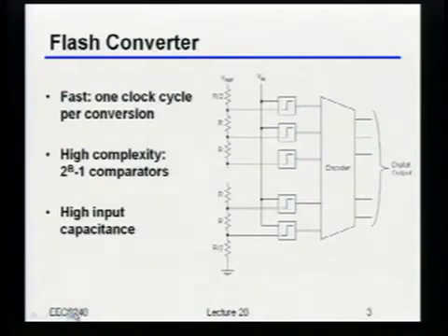So we'll see all of these things in 1 second, but this is just an additional piece of motivation as to why comparators might be interesting. We've already talked about it in the context of high-speed links, but these things are used in many other places as well. One really obvious place is in analog to digital converters. As an example, you could come up with a so-called flash analog to digital converter, where the idea is very simple. You just have a bunch of comparators. In particular, you have 2 to the number of bits minus 1 comparators.